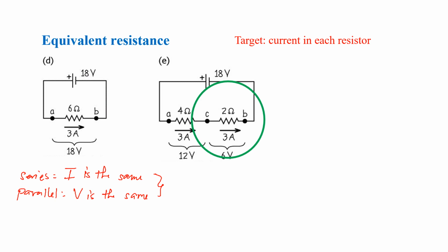In doing that, we first start with your equivalent resistance, okay? This is how you always do it. You start where you ended last time, which is just one equivalent resistor, your 6 ohms, and you have your 18 volt EMF source. We can find the current for this resistor from Ohm's law, V equals IR.